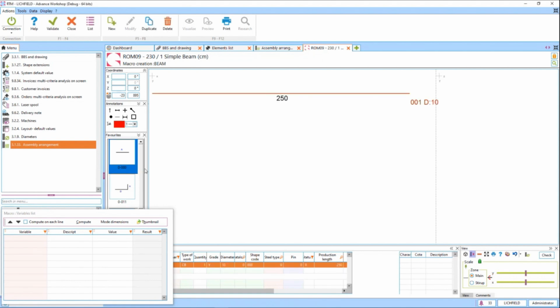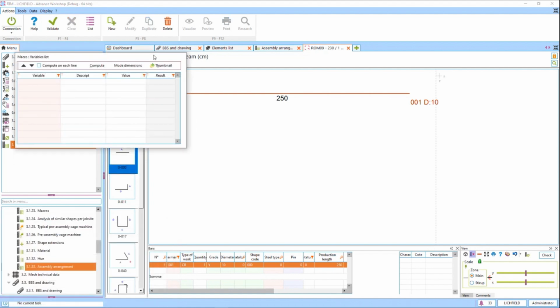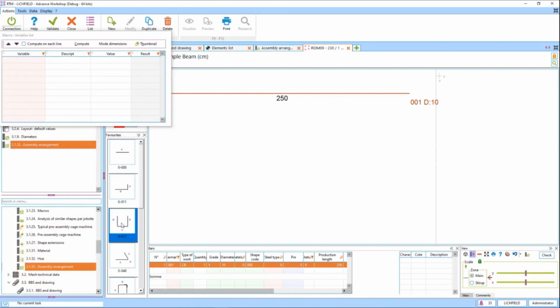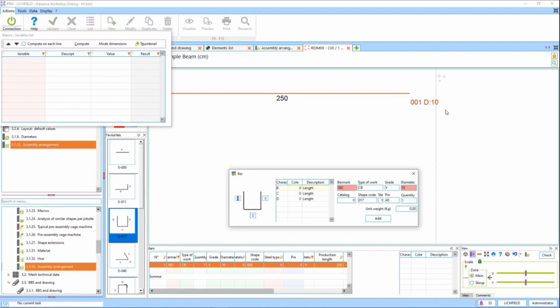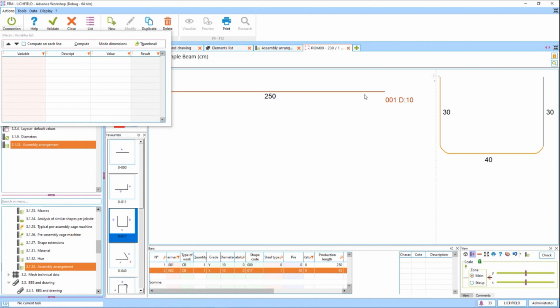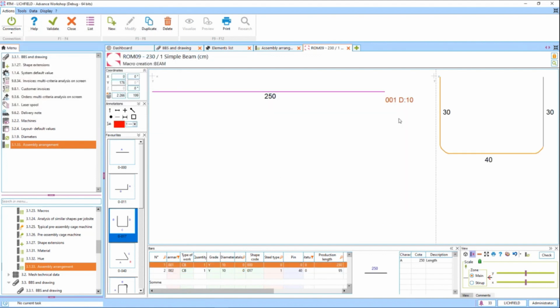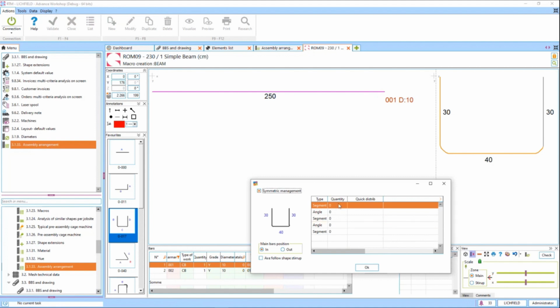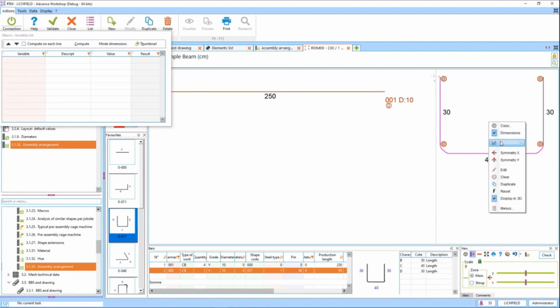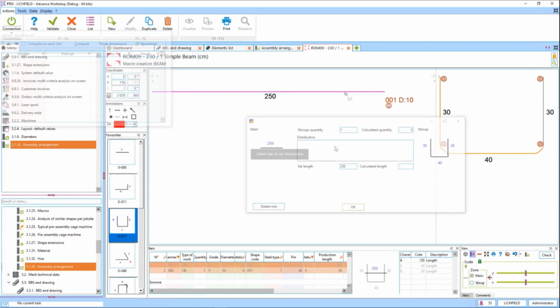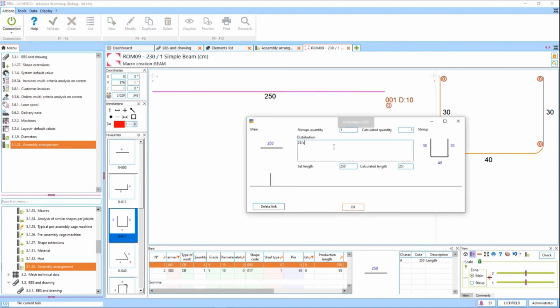variables. So as I said before, the same procedure: place in the mains, place in a stirrup, place in some dimensions for the stirrup, and then I will place in the segments where these mains need to be placed within the stirrup. So I place in 4 in those directions to create a beam, and I'll create some distributions. So I'll create in 25 by x 10, 25, press OK,